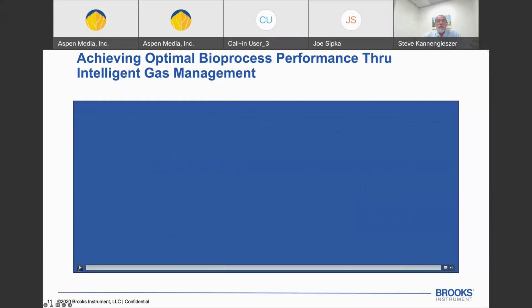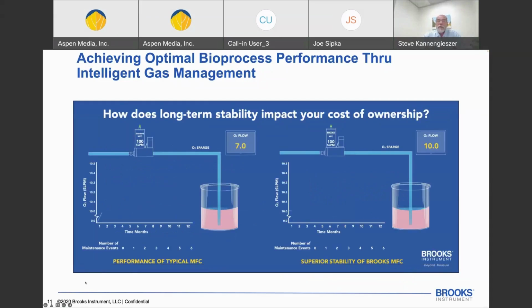If drift has been a concern for you in the past, we do have a zero drift diagnostic on board that can be programmed to raise an alarm when drift has reached a user settable threshold. You can also take advantage of the zero trending information that's stored on board the device. In this next video, Kyle Smith, our technical service manager, will review the proper zeroing of a device in more detail.